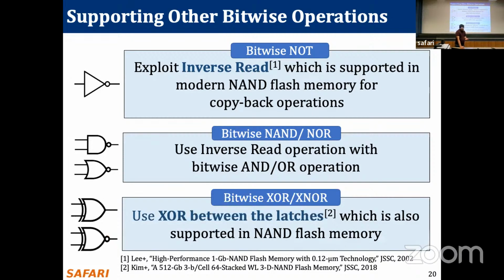And we can also perform bitwise XOR and XNOR, because this feature is also supported by NAND flash memory, which can perform XOR between the latches provided for performing triple-level cell program or multi-level cell program.